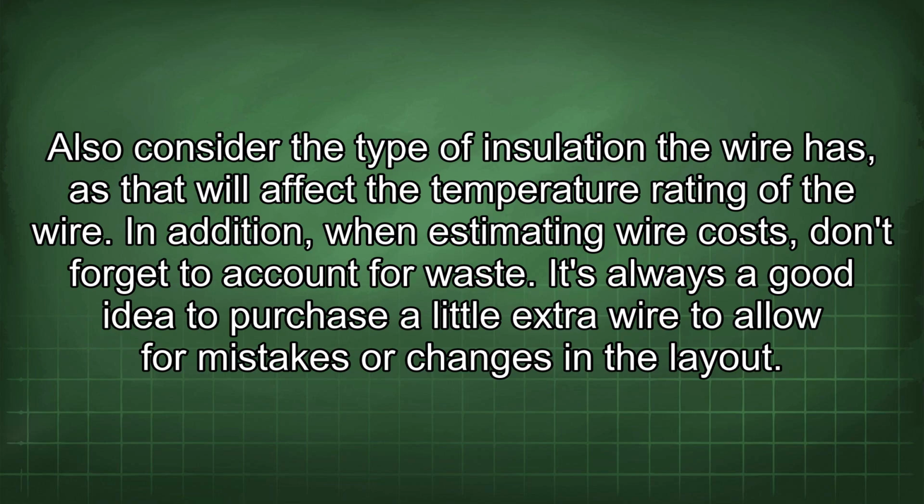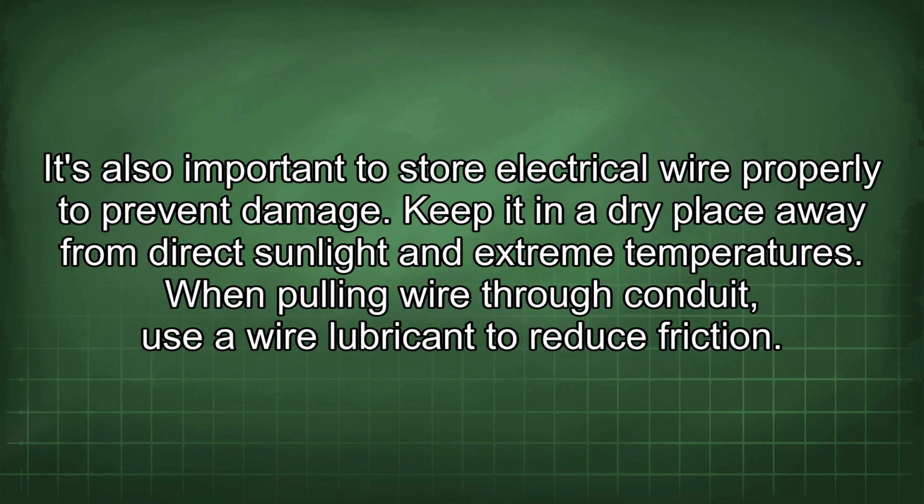Also consider the type of insulation the wire has, as that will affect the temperature rating of the wire. In addition, when estimating wire costs, don't forget to account for waste. It's always a good idea to purchase a little extra wire to allow for mistakes or changes in the layout. It's also important to store electrical wire properly to prevent damage. Keep it in a dry place away from direct sunlight and extreme temperatures.